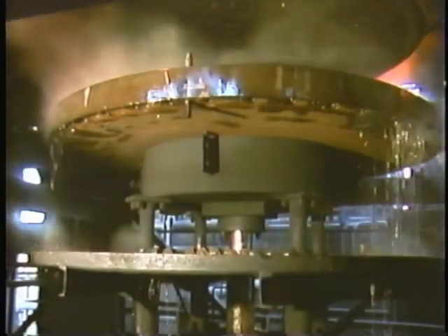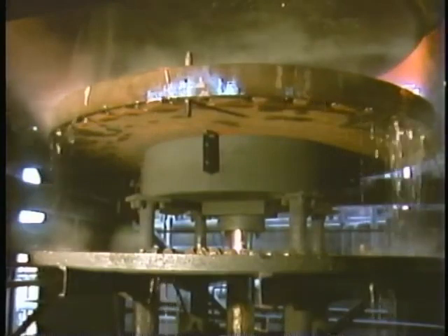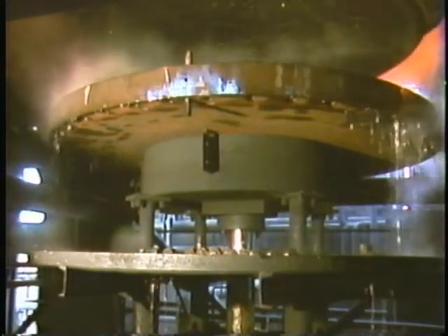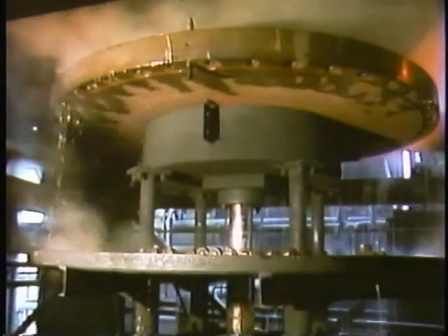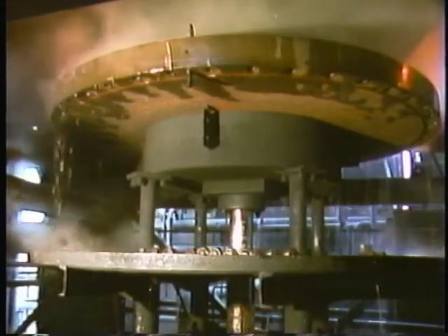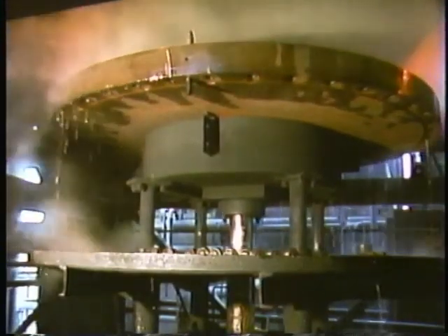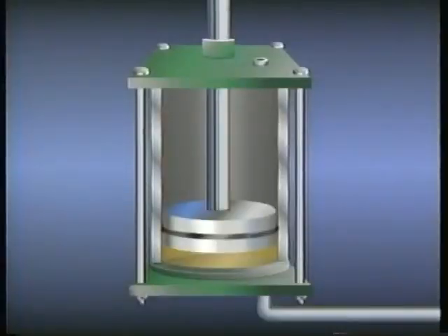This particular actuator is a single-acting one. In this actuator, fluid flow acts on only one side of the piston to raise and support a heavy load. When the fluid is allowed to flow back out of the actuator, the weight of the load supplies enough pressure to return the piston. Let's take a look at this illustration to get a better view of how this kind of single-acting actuator works. The main parts of this actuator include a cylinder, a fluid port, a vent, a piston ring, and a piston rod.